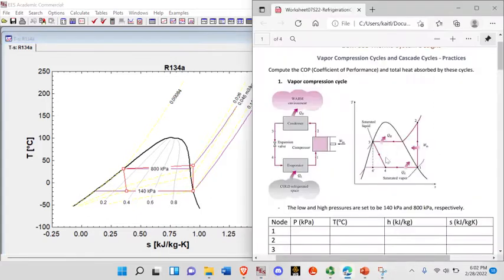So we pull up this. We'll have to make an imaginary state here. It will have the same temperature as 3, and it will have the quality of 1 because it will be a saturated vapor. So X will be 1, and temperature and pressure are the same, so we can just do temperature and pressure. Or we'll do quality. No, we need quality to specify.